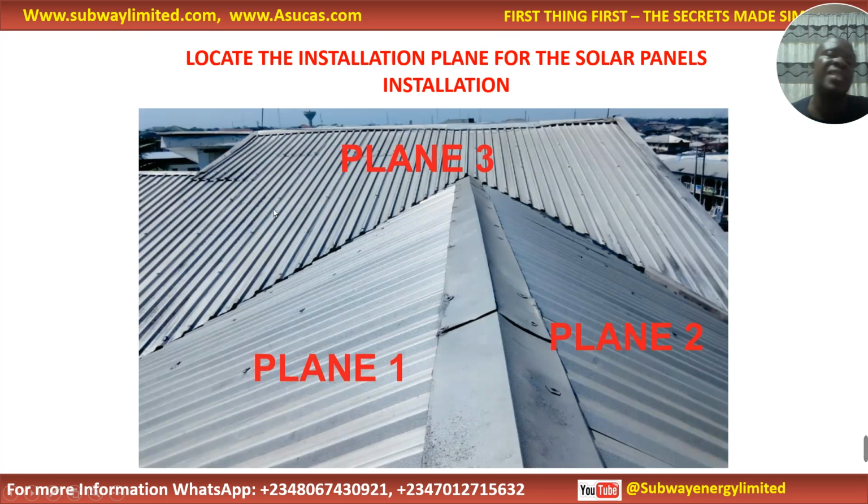So like you can see, locate this installation plane for the solar panels installation. We have different roof planes. There is a way you connect solar panels in series or parallel depending on the roof plane, because sometimes the sun will set on this other side, sun will rise on this other side. So you have to study the sun movement in a particular location to know how you connect your panels either in series or parallel in a particular roof plane. So we call this the roof plane. You can say plane 1, plane 2, plane 3.